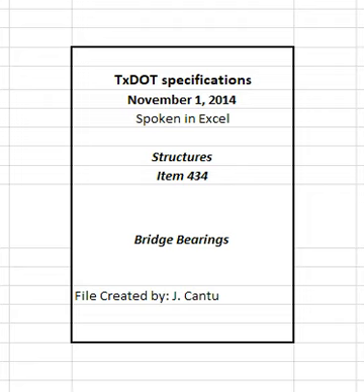Disassemble bearings for visual inspection after testing. Replace or repair any bearings that reveal malfunctions such as liftoff, galling between components, excessive deflection, yielding of steel, wrinkling of stainless steel, and flow or bond failure of PTFE. Perform testing to validate performance of replaced or repaired bearings as directed. Costs associated with testing project samples failing to conform to these requirements are borne by the bearings manufacturer. This cost will be assessed at the rate established by construction division at the time of testing.